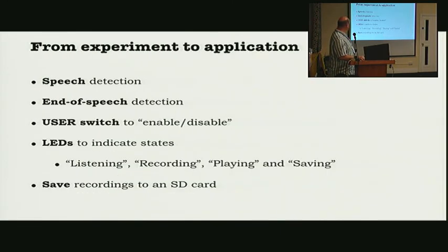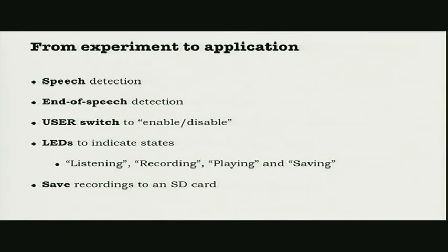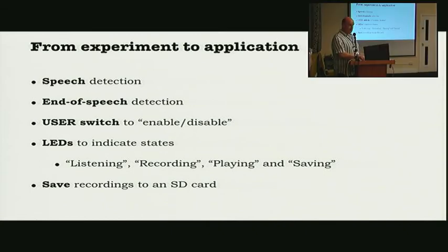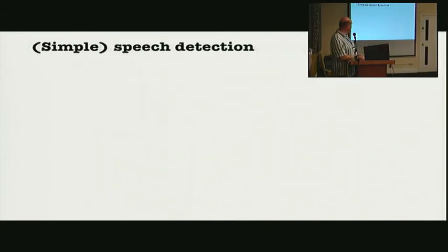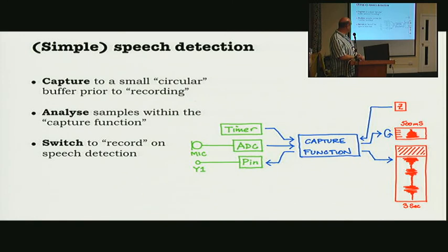I'll skip that bit. That doesn't give me my real-time application, because I don't want to press a button to make recordings. I want this to be real-time, so I need some speech detection as well. The way I do that is that when I'm recording, I'm using a very small buffer in a circular fashion to record audio, but because I know the silence level, I can make an estimate of whether someone started speaking. So that little buffer acts as a recording trigger.